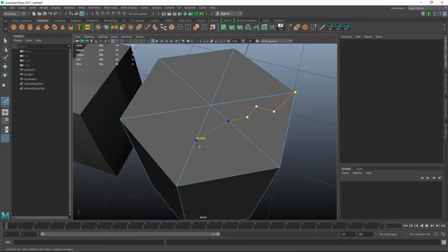And if I do that and hold the shift key, you can see that these little dots with percentages show up. This is a cool way to, say, make a ring at 40%, to be more precise when you're drawing in topology. If you right click, that will actually complete the tool.